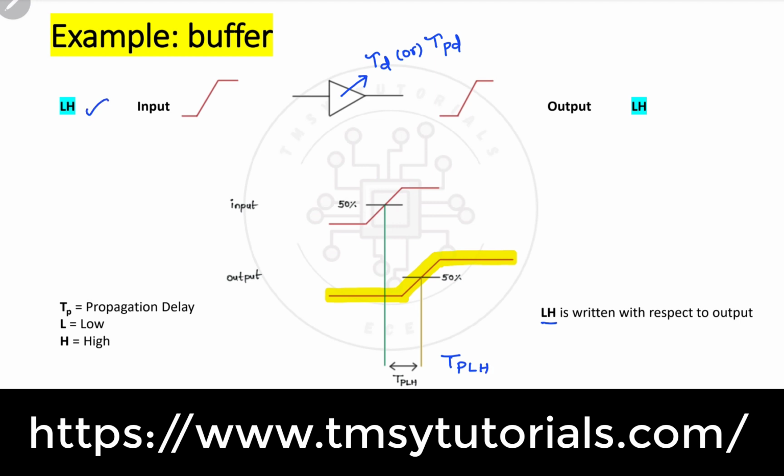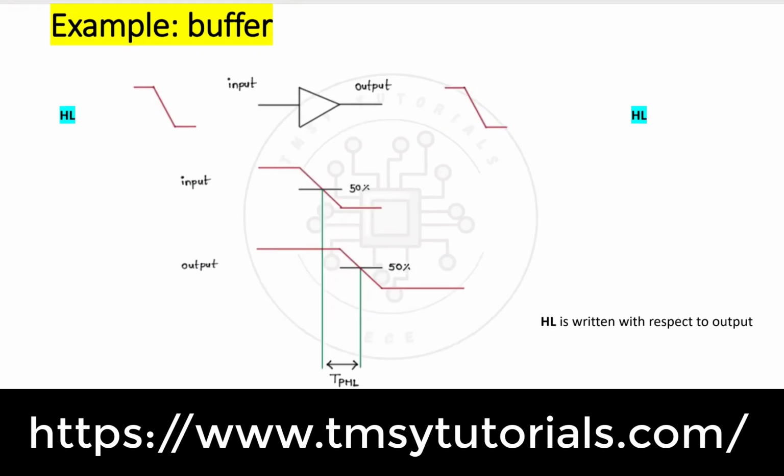Now let us take the input from high to low. The same example, the only change is that the input is coming from high to low. So the output will also be high to low. Whenever the input is moving from high to low, the output will also be moving from high to low, as this is a buffer. Now here it should be written as TPHL. Why? Because initially the output is high and after that it is going low. So high to low, that's why TPHL.